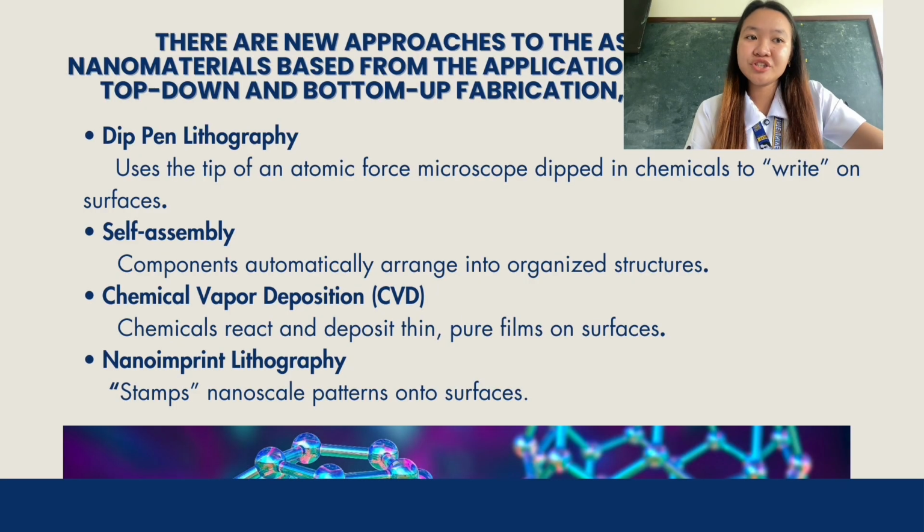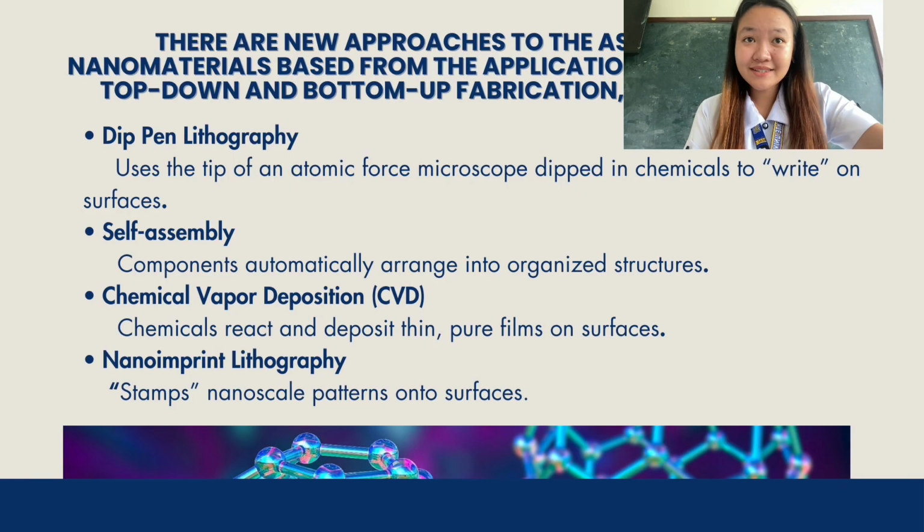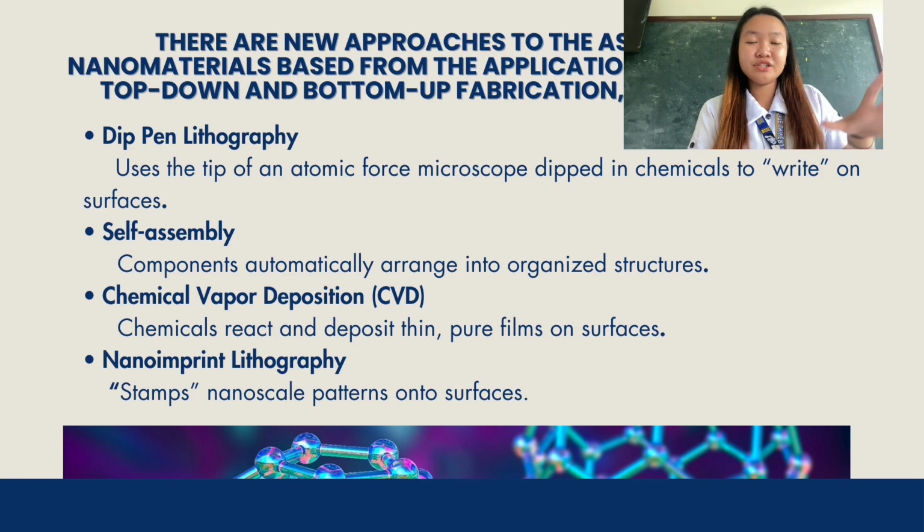Microchips, LEDs, and lasers require this high accuracy. Next, we have roll-to-roll processing, which produces nanoscale devices on long, ultra-thin rolls of plastic or metal. A continuous sheet of material passes through machines and receives nano patterns or coatings.